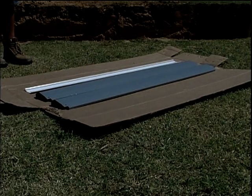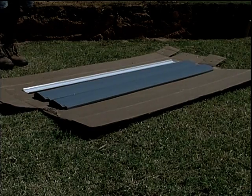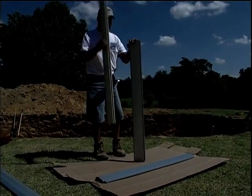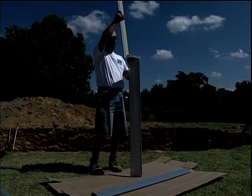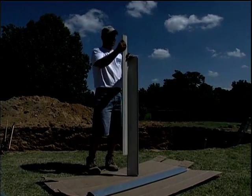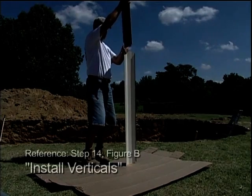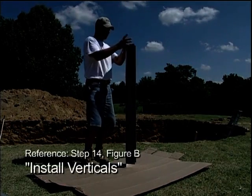There are different configurations of the end verticals. Some verticals are a 3-piece unit that must be assembled. Others are 1-piece verticals that are ready to install. The 3-piece assembly consists of 2 sides and 1 center strip. In order to assemble, slide the center strip's end beads into the matching opening on the side pieces. Please reference Figure B, Install Verticals.